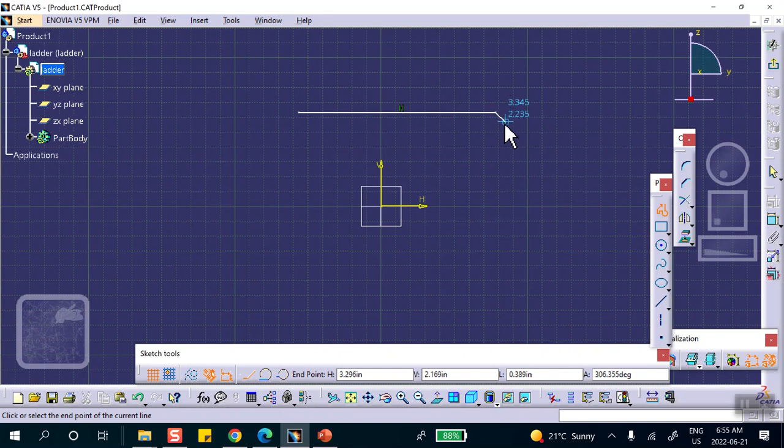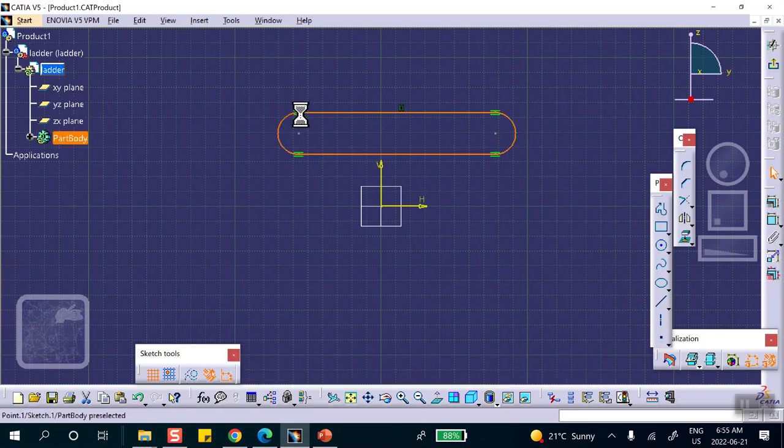Now notice that I was going to make a circle here, and I missed the opportunity. Left click, hold down, and drag a little bit. But that's okay. You can always go to the sketch tool and clear it up right there. See that? You come down here, left mouse button down, drag it a little bit, and it turns into a circle. Otherwise, you do it with what I just showed you.